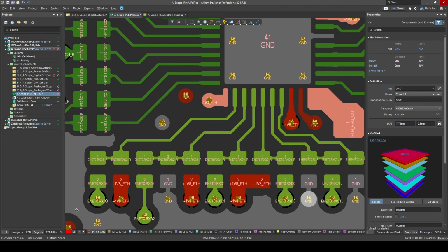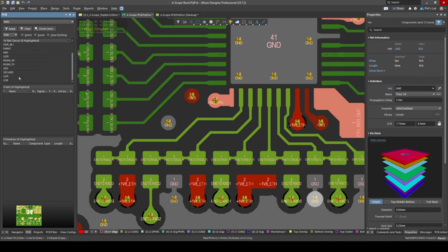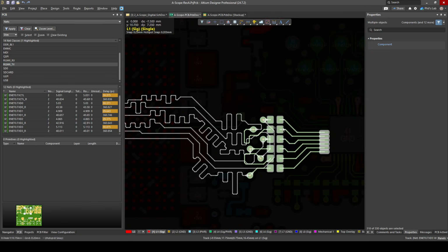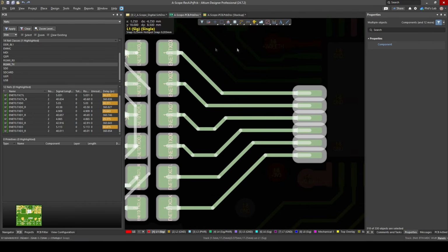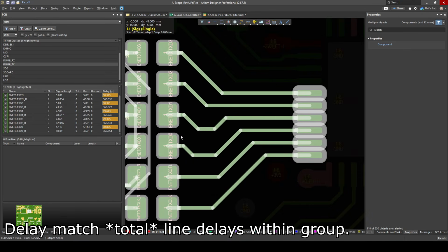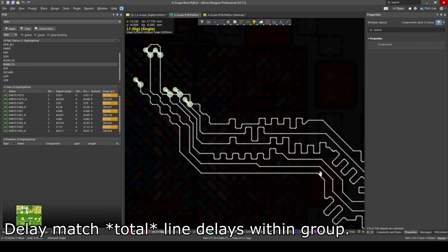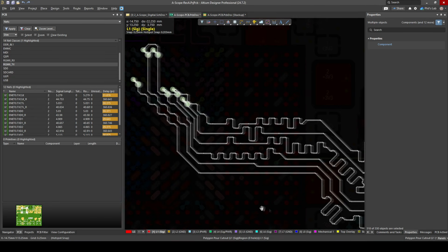So depending on what ECAD tool you're using, for example, in Altium Designer, I can set up net classes and look at, for example, the TX groups, and I can either do these as X signals or as not, where I can combine them with the series termination resistors. But you can see the trace lengths before the series termination resistors are matched. So these are all about 30 picoseconds in time delay, and also after the series termination resistors, these are delay matched, that they're all about 360 picoseconds in delay per line.